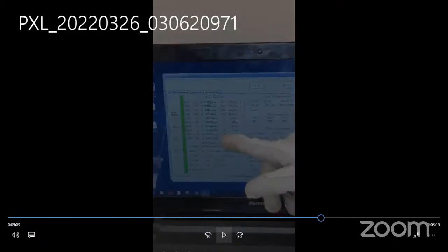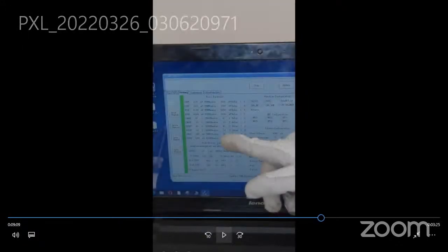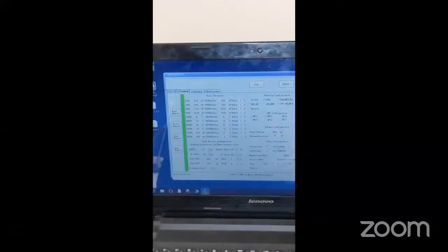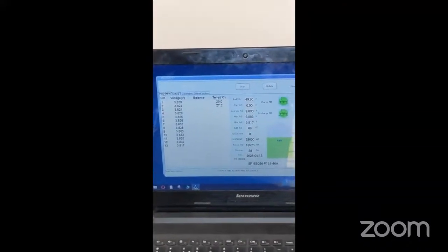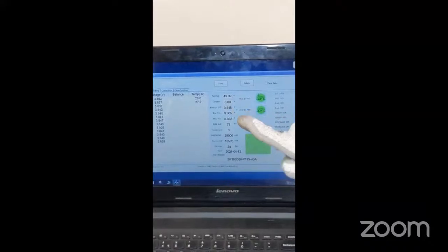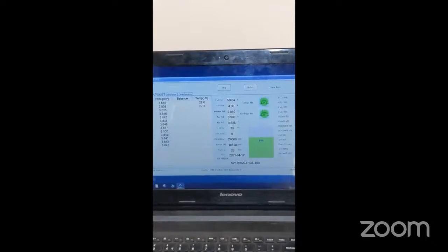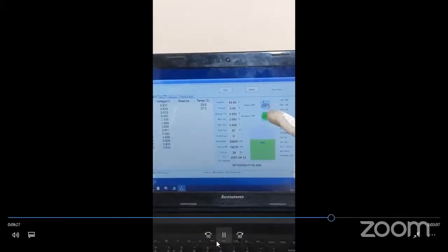Now first we look at the charging part. If the charger is providing current which is above the limit for the battery pack, what happens in the BMS? We'll just look at it. Now let us see first charging. You can see on the current window there is 4 amps going in, which is above the parameters we have set. You see suddenly there is a change. So this is what happens.